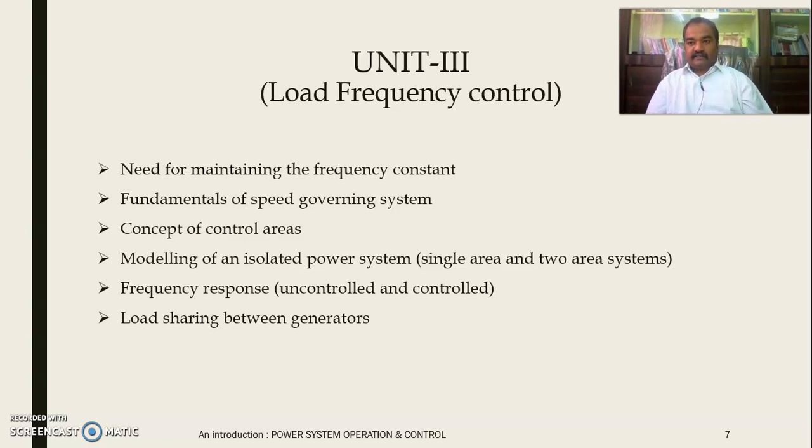And we will try to develop a mathematical model of the biggest influencer of frequency. As we all know, the load is a primary influence which influences the system frequency. So we will develop a mathematical model of change in frequency with respect to the change in power for an isolated power system, and also we will develop a mathematical model for a two-area system. And thereby we will try to understand the load sharing between the generators so as to maintain the system frequency.